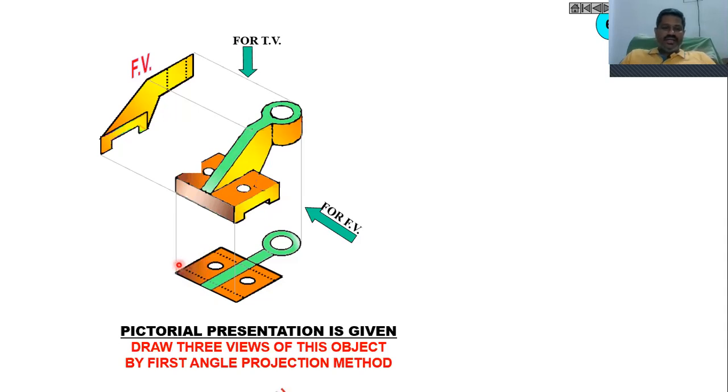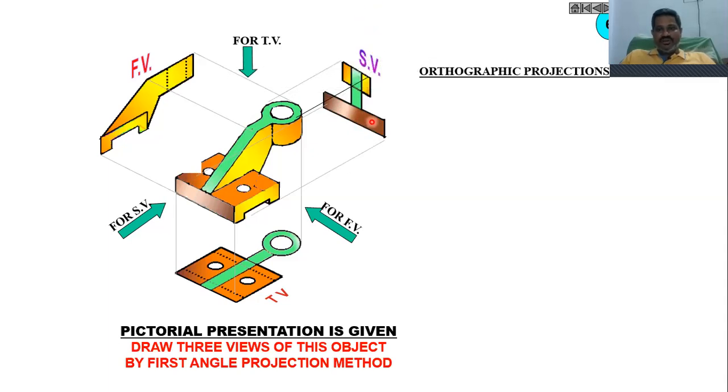So now let us draw the left side view like this. Now it looks like this. So you will find this face with this height, and you will find the rectangular block here, and similarly you will find two dotted lines here also. To represent these two holes, we have two dotted lines here and two dotted lines here, but that is not shown here. Let me check whether these dotted lines will be shown on the side view while drawing the projections.